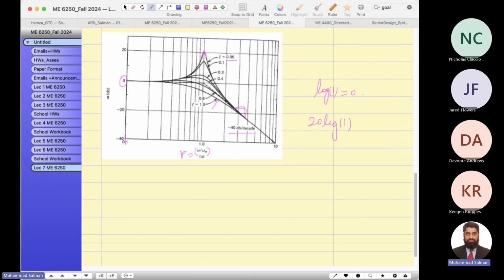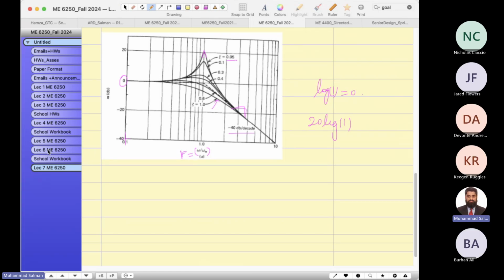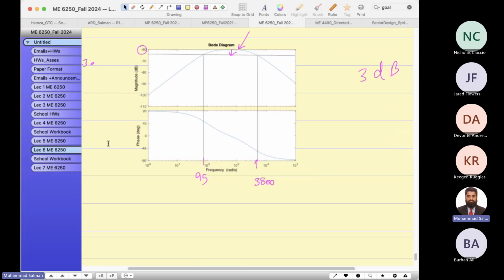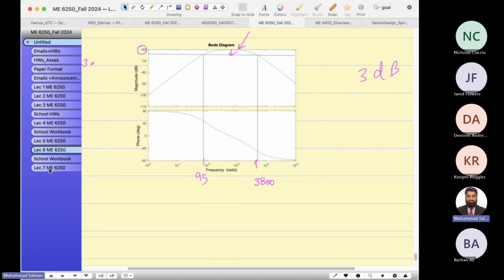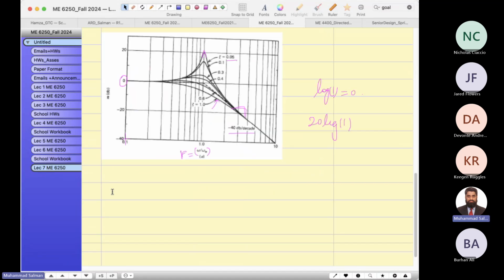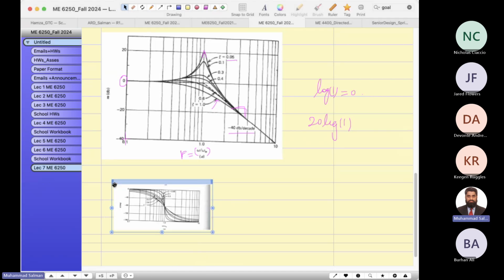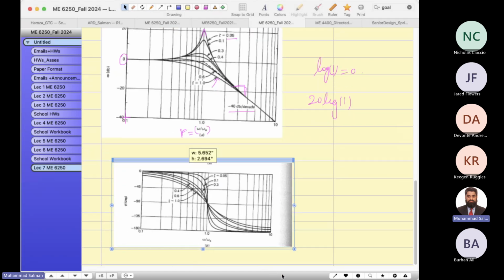And how would you draw the phase plot? I believe I showed you this phase plot in the previous video. You will see the deflection from a certain angle to a new angle; if you see a 90-degree phase change, then that is the point where the resonance is occurring.